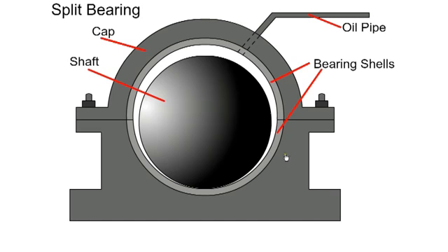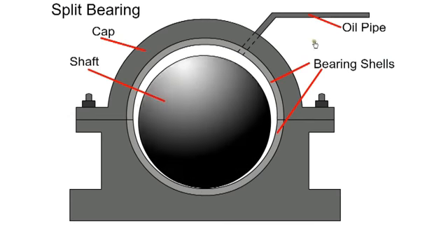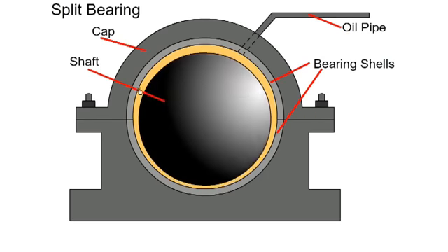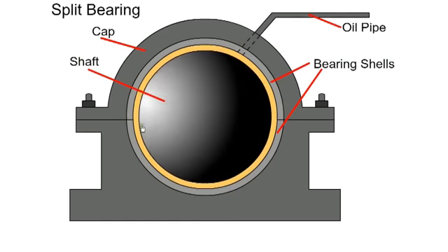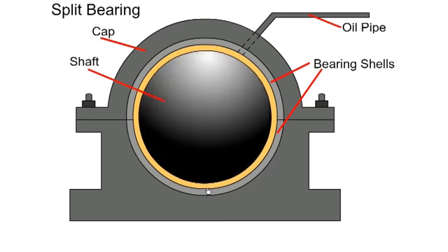The bearings in an engine use hydrodynamic lubrication. There is a very small clearance between the shaft and the bearing journal. When the engine is started, the shaft is running without lubrication for a short period. When oil is introduced, a film of oil is dragged around by the shaft, and the shaft is then centered in the bearing housing. Now we have hydrodynamic lubrication.